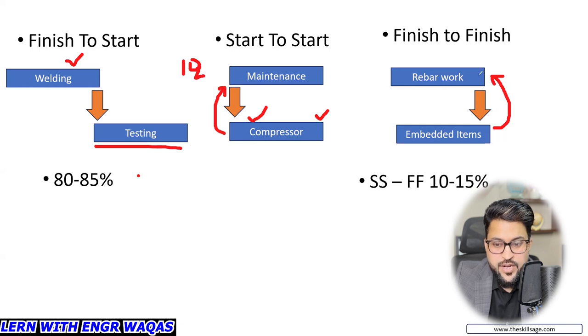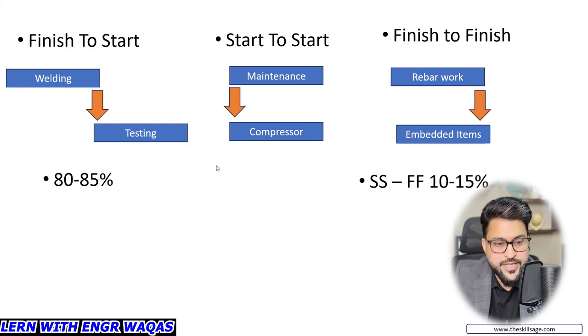This is depending on the rebar work, right? So this is the successor activity. The successor activity is usually where the arrow is pointing its head, and the tail of the arrow is connecting with the predecessor activity. That is a usual perception and pattern you can identify easily when you see your bar chart area. The second most important point: the successor activity is always depending on the predecessor activity status. In a finish to start relationship, this is the predecessor status. You understand? So it is very important to understand which activity is predecessor and which is successor.